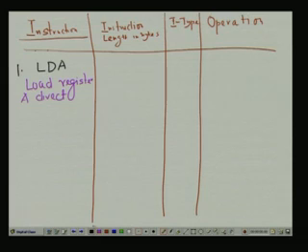The instruction type is, we know, MRI, memory reference. The instruction length in bytes is 2: 1 byte for the opcode, 1 byte for the address. The operation will be LDA, load register from memory, M address. So, from memory the data is loaded to register A. STA is actually the reverse one.